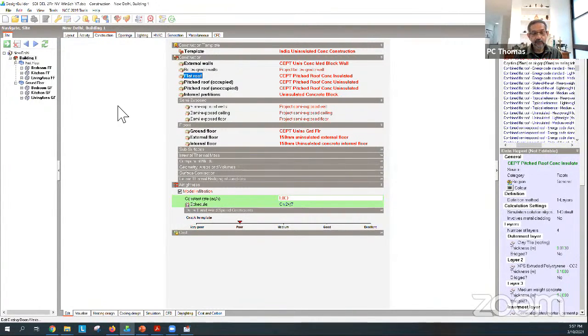And in wooden construction, you're looking at the gap between the wall and the floor and between the wall and the ceiling. In concrete construction, that's not a problem. You have very, very tight gaps when you've got a concrete floor and a concrete wall. There's nowhere for the air to go. But then your gaps are all the gaps around the windows, around the doors, underneath the doors. Those are the areas where you have gaps. Now you can model them.